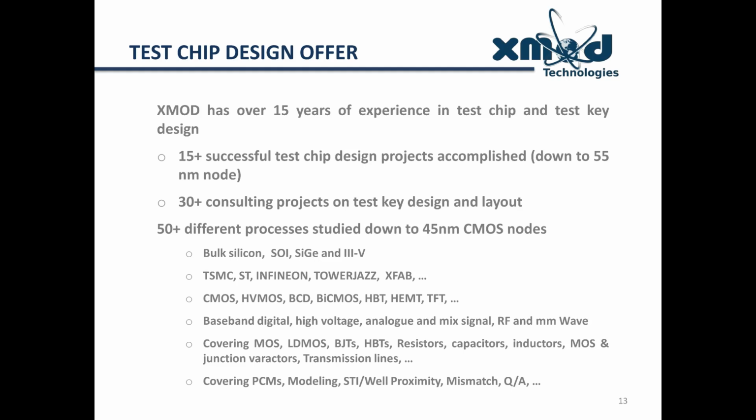Test chip design also is dedicated to baseband digital, high voltage, analog and mixed signal, and RF and millimeter wave applications. And those are covering MOS, LDMOS, BJTs, HBTs, resistors, capacitors, inductors, MOS and junction varactors or other transmission lines, and basically all the available device types on the technology process.